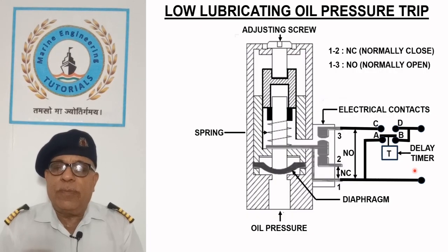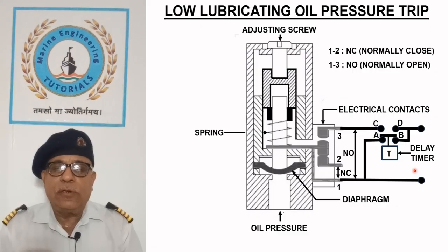Air compressor is equipped with an attached lubricating oil pump driven by its crankshaft. When the compressor is started, it takes a few seconds to build up the oil pressure. For preventing damage to bearings during the absence of lubricating oil in the beginning, the compressor is operated in the unloaded state during this period.